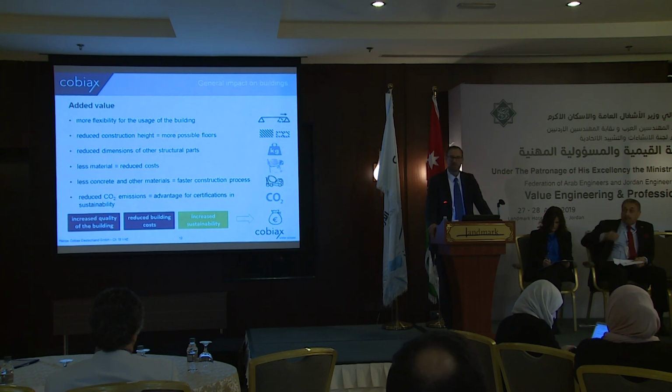If you reduce the weight and the dead load, that has an advantage not only for the slab itself, but for the whole structure of the building. So we can reduce dimensions of columns, of walls, down to the foundation and optimize all the structural parts, especially in regions with seismic actions, because if you take load out of the total structure, this also helps with the calculations for seismic actions.